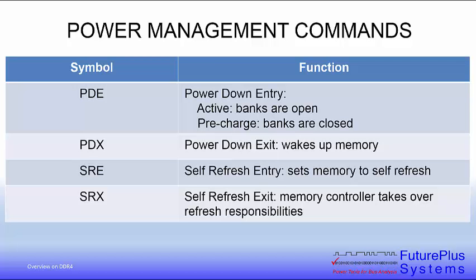SRE stands for self-refresh entry, which is when the memory controller tells the memory to enter into self-refresh mode. This is when the DRAM is responsible for refreshing itself, as no refresh commands will be issued from the memory controller. SRX means self-refresh exit. This is when the memory controller comes back and takes over the refresh responsibilities.